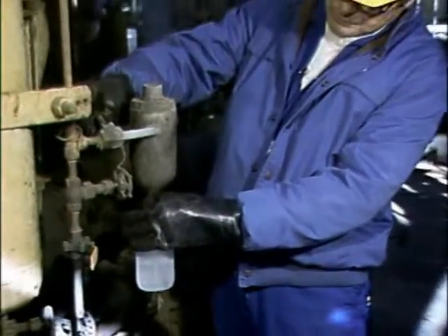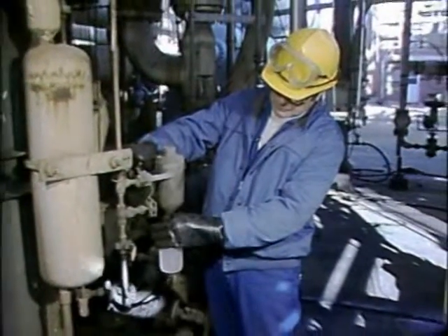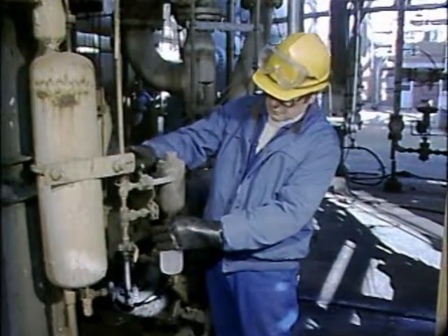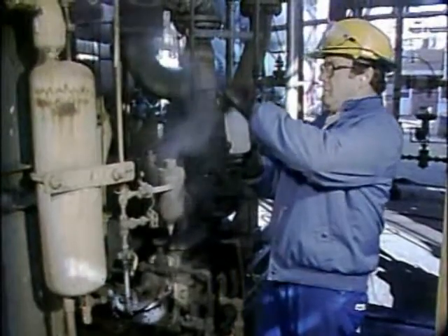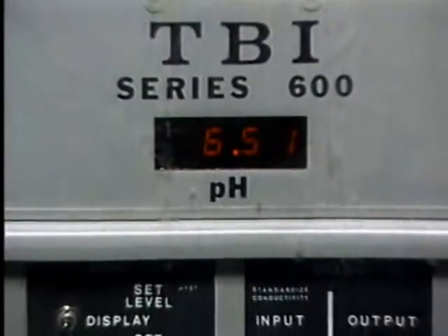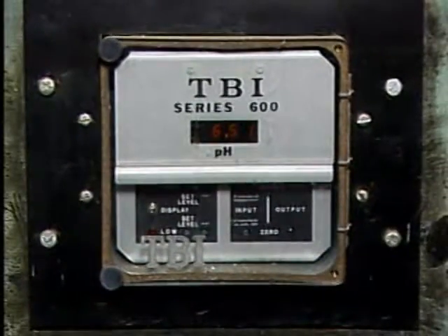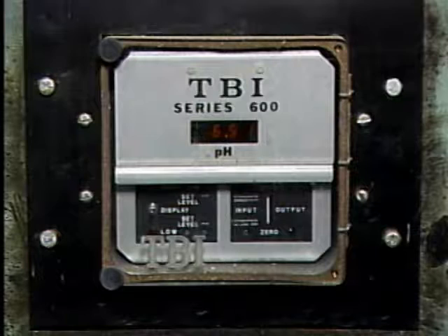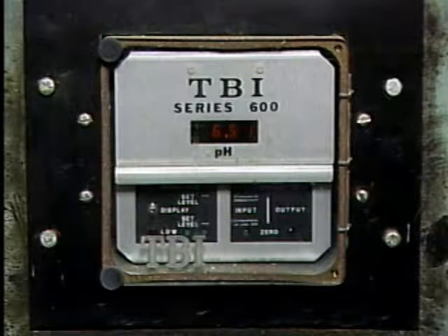One way to check for contamination is to take a sample of the lower pressure fluid and test it for the presence of the higher pressure fluid. In some cases, contamination in the sample can be seen. In addition to sample test results, conductivity and pH readings of cooling water may indicate a tube leak. If there is any indication of contamination, it's important to determine the source of the problem and take the appropriate corrective action. Kettle-type reboilers are a type of shell and tube heat exchanger.